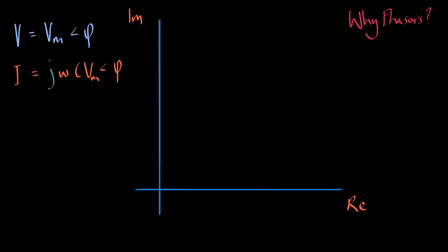Knowing then the phasor representation of the capacitor for both voltage and current, they can now both be expressed diagrammatically. First, the voltage, this time at some angle phi, followed by the current, 90 degrees removed. Note that this is the exact reverse orientation to the inductor.